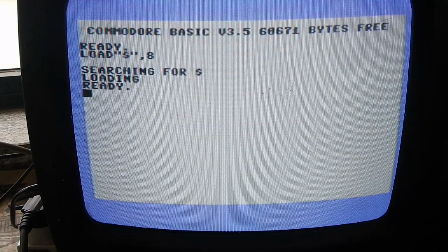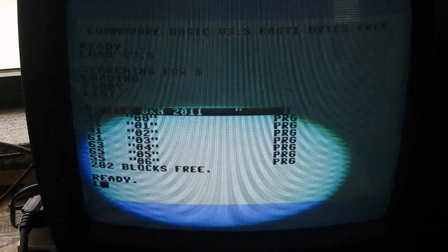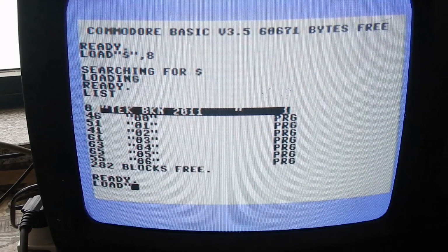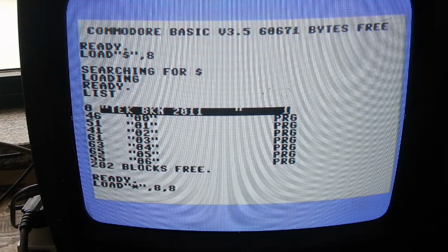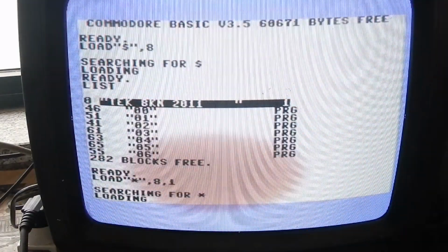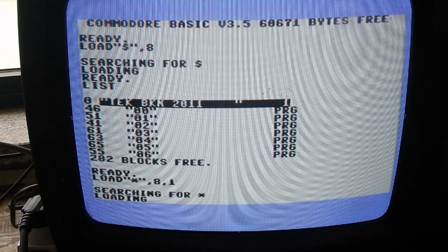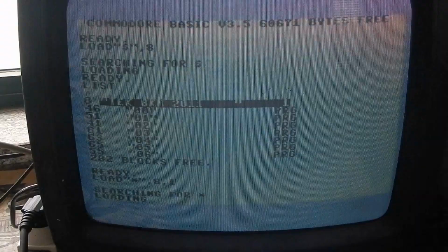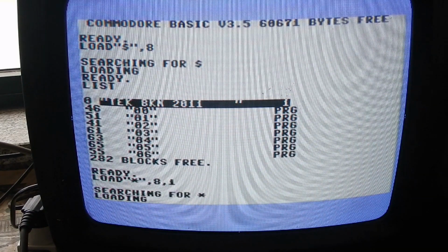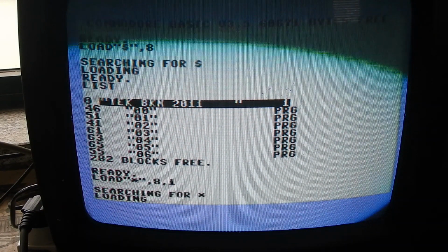As a final test, I ran a demo. These fine pieces of programming art exploit most of the strangest features and bugs of their target computers. They use the CPU undocumented opcodes and implement fast loader methods to load the new parts from the floppy drive. I think that there is no better test for a replacement IC than to be able to correctly run a demo from start to finish.